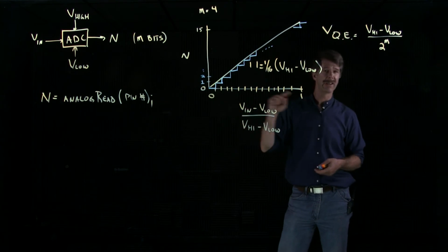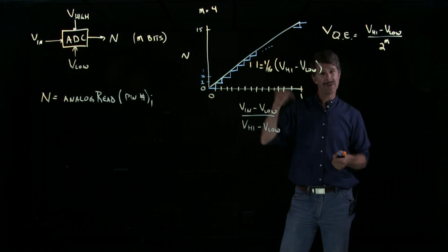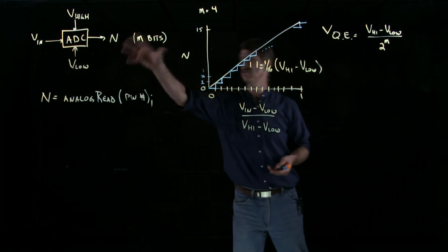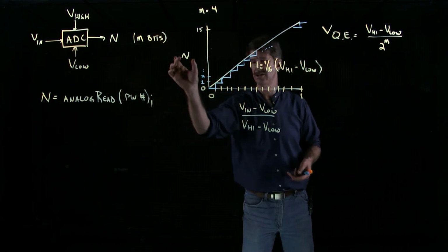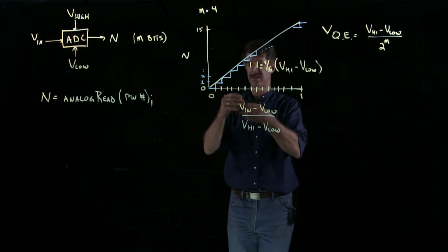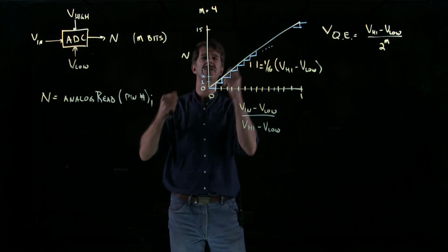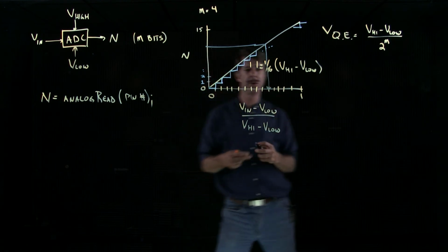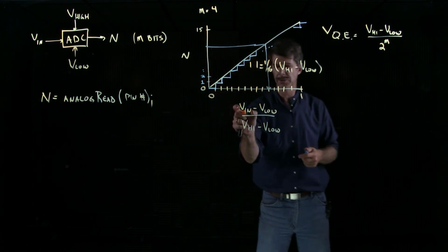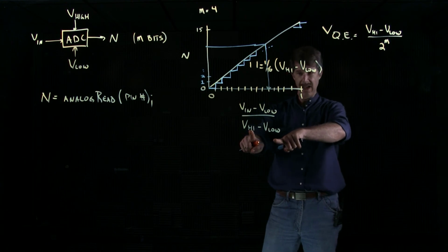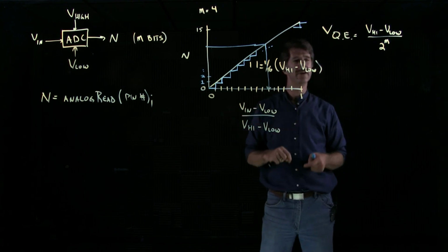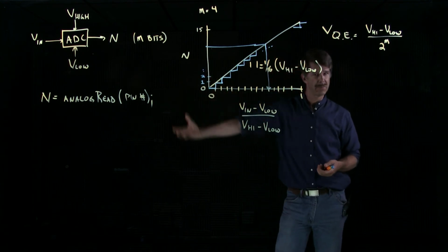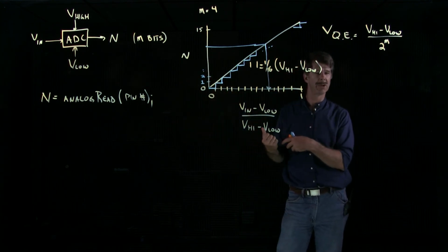So you also need to write down that math so that in the end you can have a function which says read temperature, and it goes through all of this, reads this integer, does this operation, takes some integer that you get, turns it into some voltage, then having that voltage, which of course you need to know V low and V high to turn this into Vin, then it takes an equation for Vin and produces temperature and hands you back a temperature.